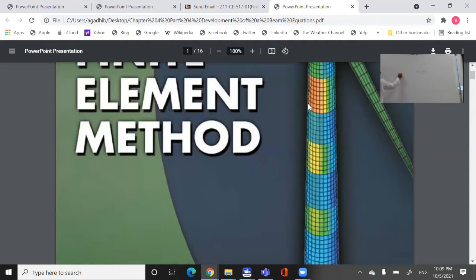Okay, you have this, and after bending, this is normal. After bending, it becomes like this. Of course, it goes down. So the strain here, we are talking about this strain. This is called U. You see? The rotation, because now there is extension here, this is like compression and this is tension. So how do you relate U to the vertical independent variable? Because our independent variable is the deflection, which is V.